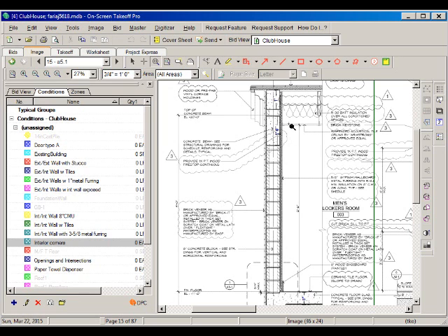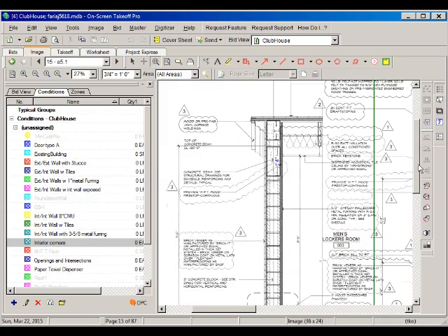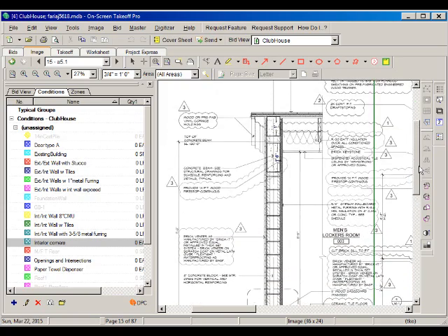It goes past the suspended ceiling all the way to the top. That means that we will have paint only to 8 feet 6 inches, but when we estimate the area for the wallboard, we have to go all the way to the top. So we will have to make a distinction between the height that's going to be painted and the height of the entire wall.